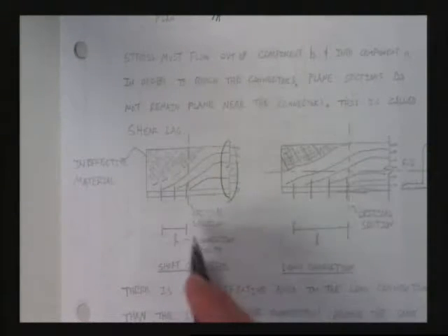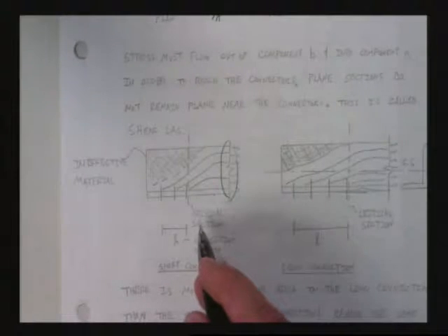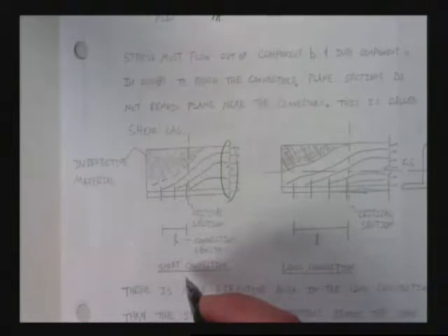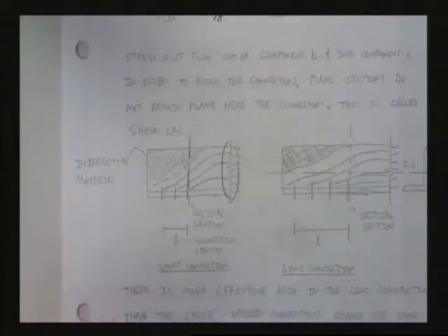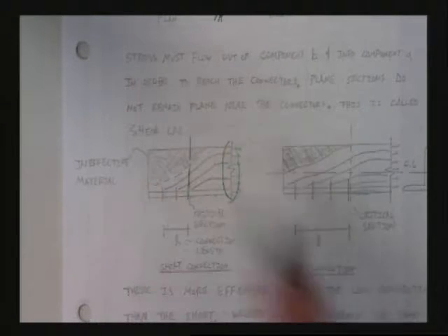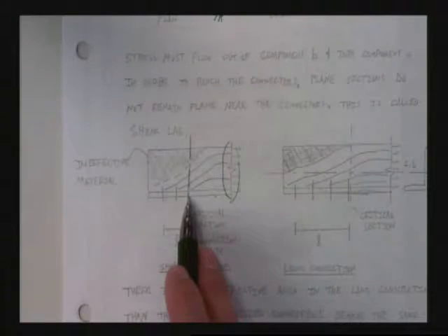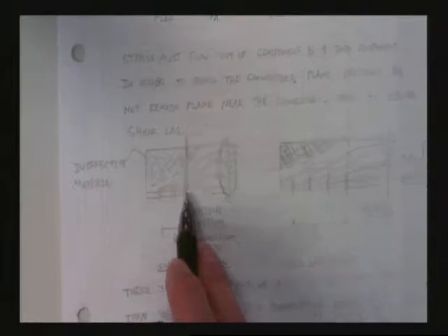And why we care about this is that if we were going to look at fracture, we would say fracture is going to happen here. How do I know that? Well, remember, I proved that before. I proved that for a single number of bolts, there's going to be the most stress on this cross-section. If you don't remember, look back at your notes, all right? So it has to happen here.